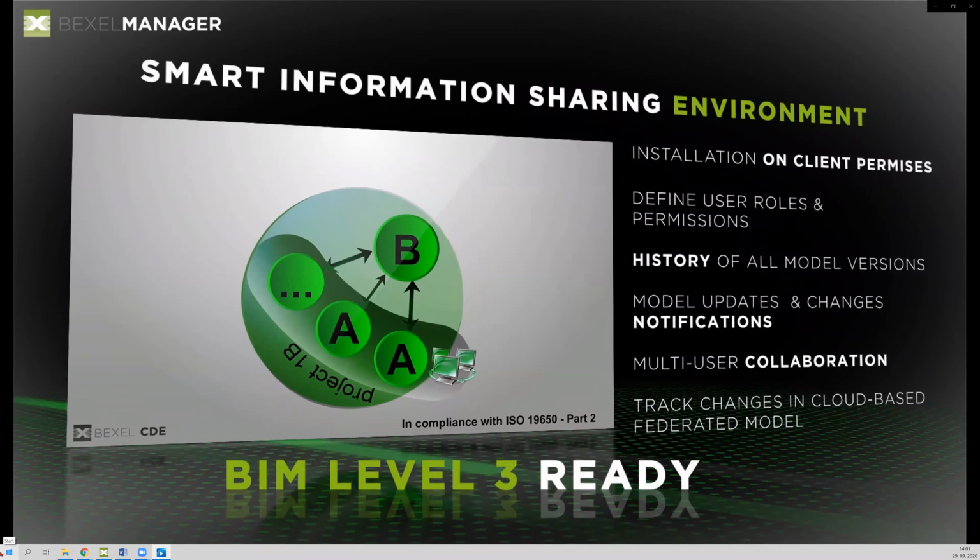You can do that by using the commands within the Manage tab, for example, project information and sources. To review your project visually, you can use the Building Explorer, where you can see that it is divided in 4 different tabs, and you can review your project by categories and families, spatial structure, or different systems.